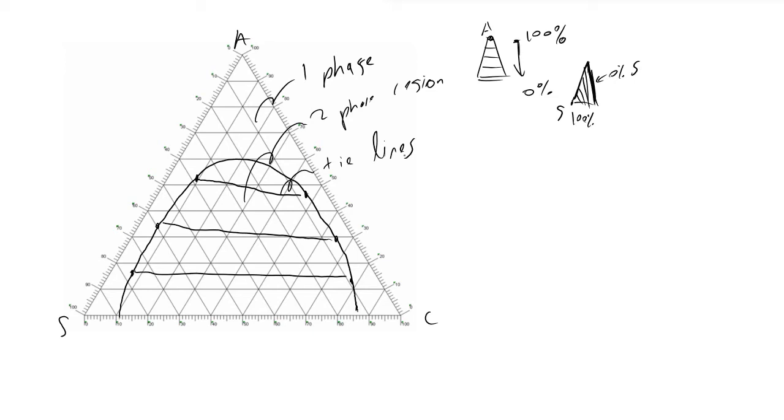And the next step that we will do is plot the points of the compositions that we know. And so we know that our solvent is pure, so we can label this point S, and we know that our feed will consist only of carrier and solute, so it must exist as some point on this AC line in our equilateral triangle.